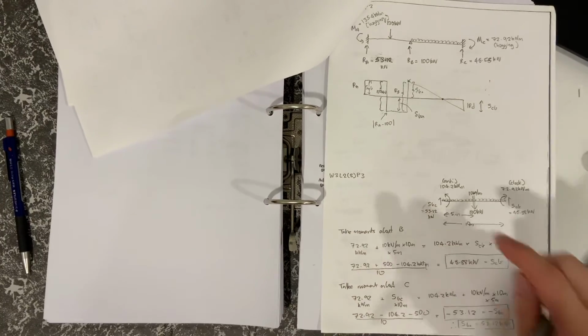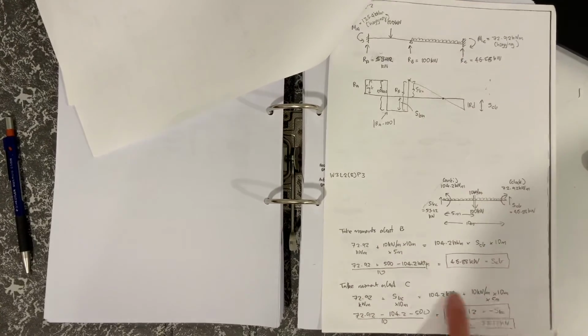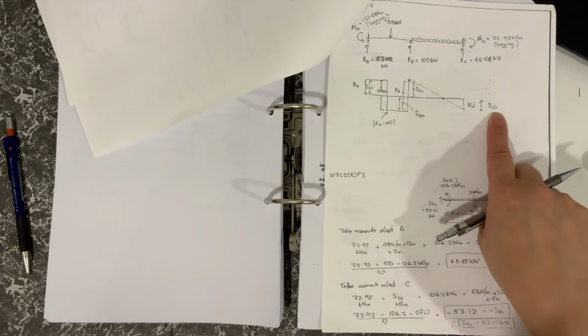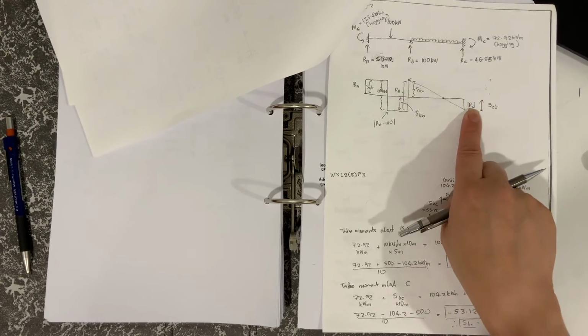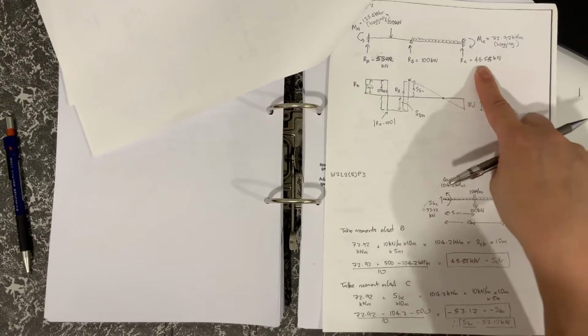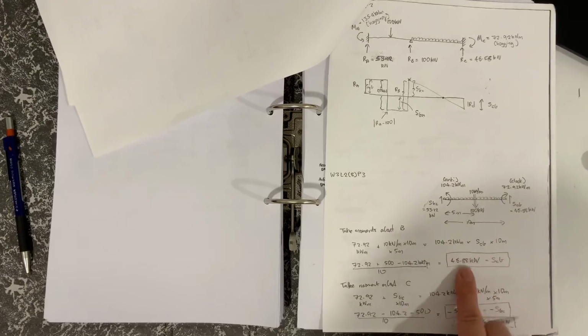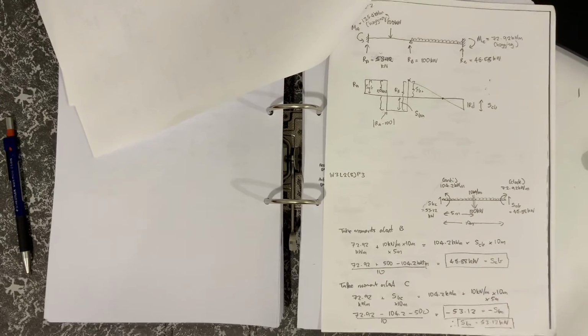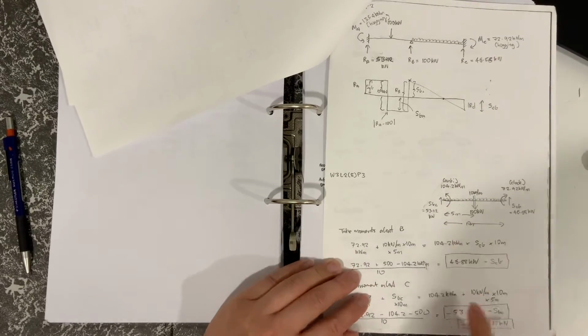and that will give you your 100 kilonewtons. And then back to the other side, we've worked out what the SCB is on this side here, and that's also just the reaction at C, which you could calculate to be 46.88. So you can see that all drawn there.